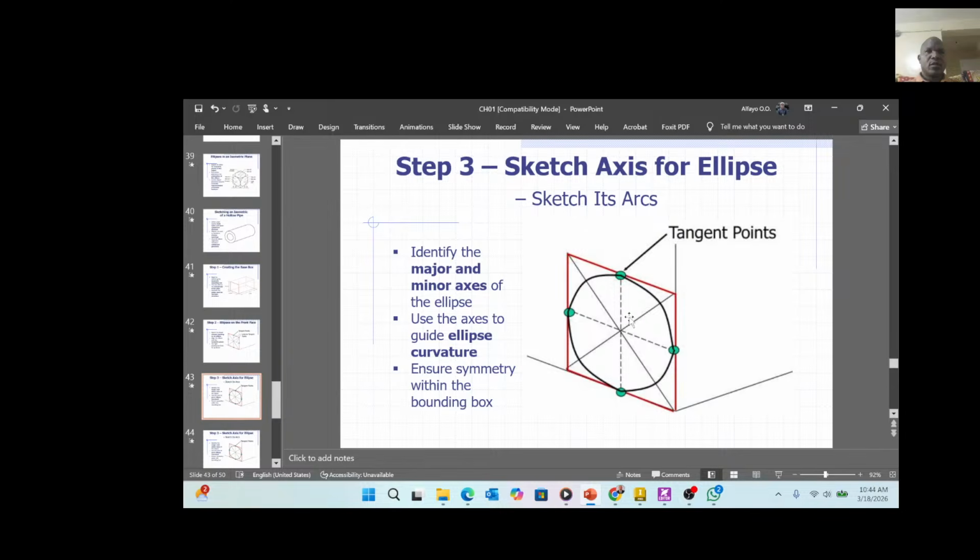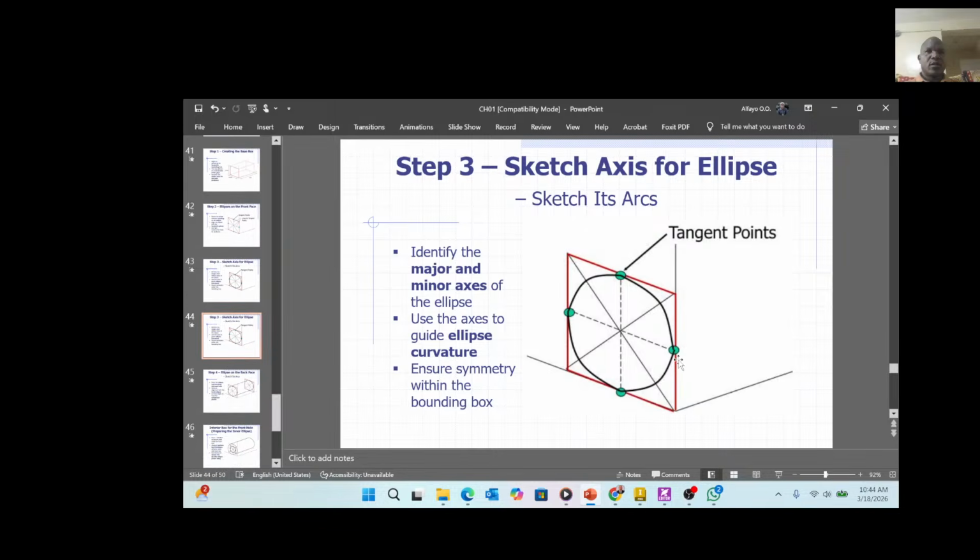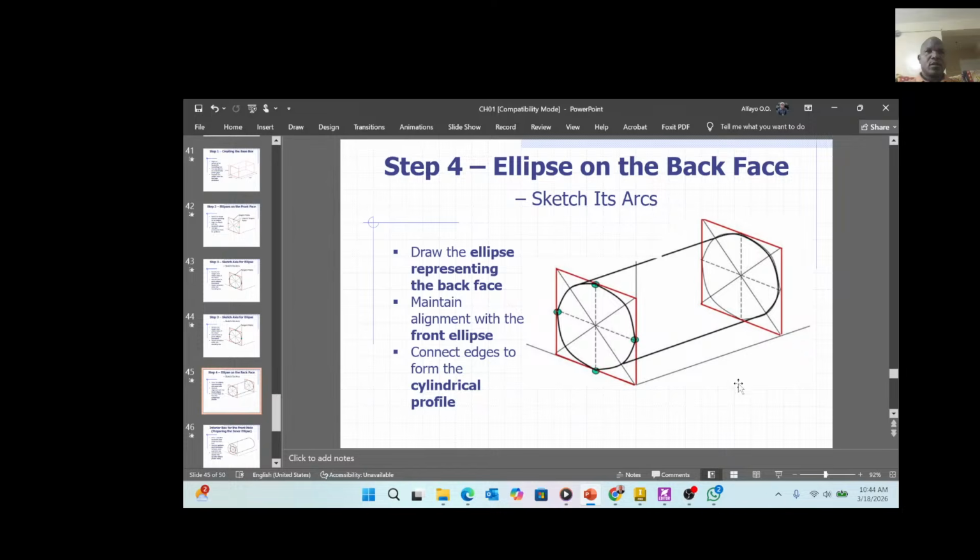In this case, this was our front view. And we need also the internal diameter now. In the same manner, pay attention, we've just worked that one. But before this one, this has to be extended to a distance of what? 100 millimeters. So from this point, draw a straight edge parallel to this edge. And also from here, a straight edge parallel to this base, it's an isometric at 30 degrees actually. This is how it's being drawn. Up to that end, from this point and from that point.